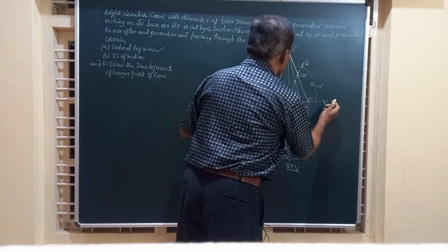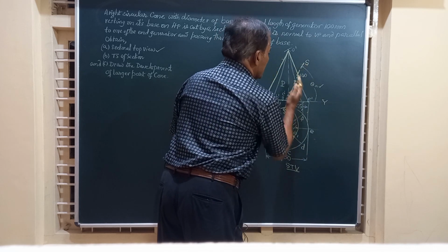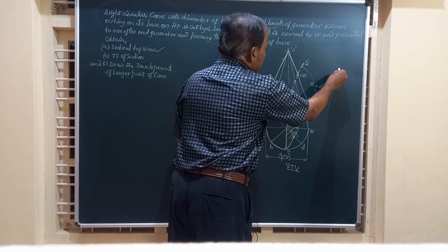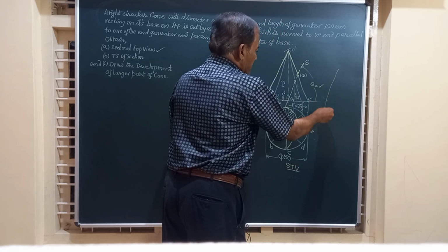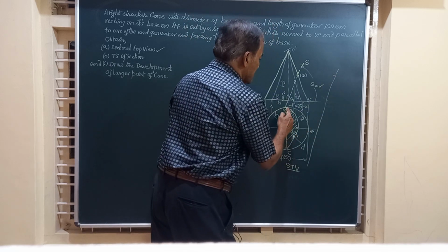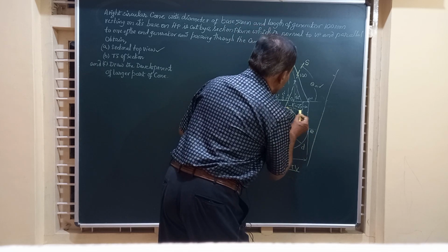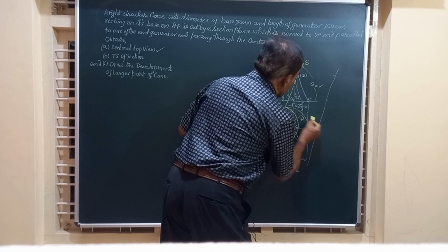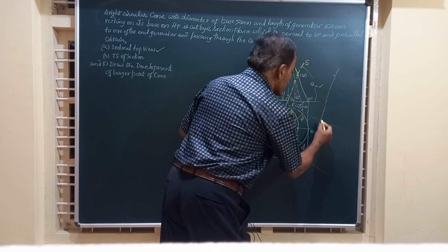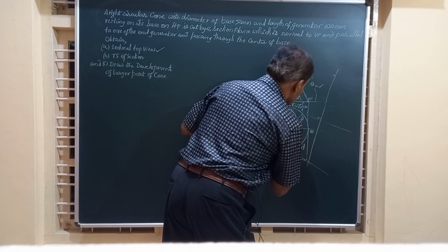You can draw this to the right side of this because this is retained, and we are going to hold the mirror parallel to SS. We can draw this true shape of the section by drawing another line parallel to SS and transferring all these points, that is on the base, and all these perpendicular to this. So friends, we are just going to draw these lines perpendicular, all these lines are perpendicular. On this we are going to mark these points.